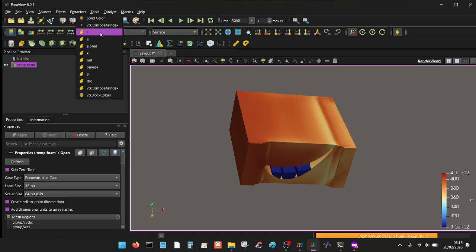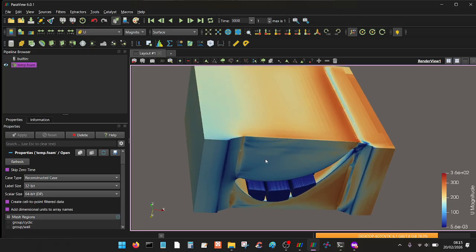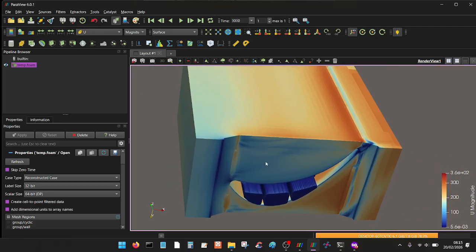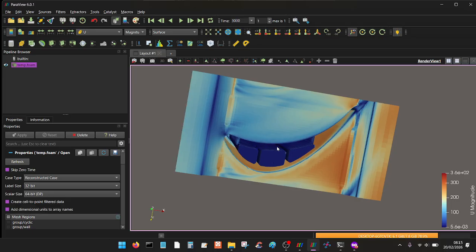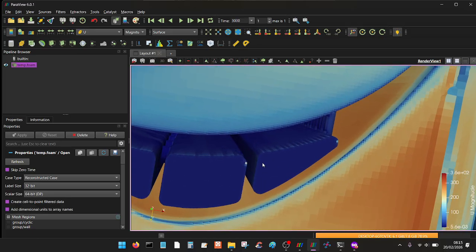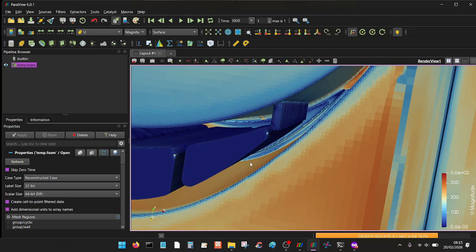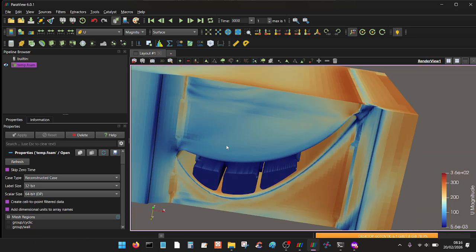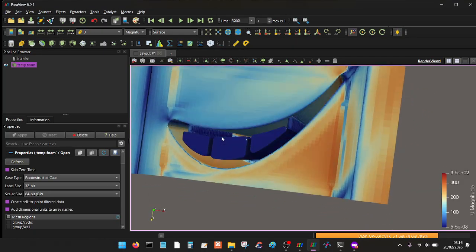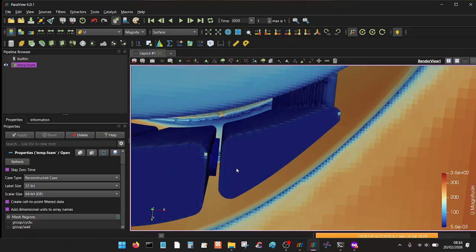And we can switch that to velocity. You can see the cooling flow is as it should be, which is quite a low velocity, although there are a few dodgy points there which are wrong. It seems like a slightly sensitive boundary condition, this one.